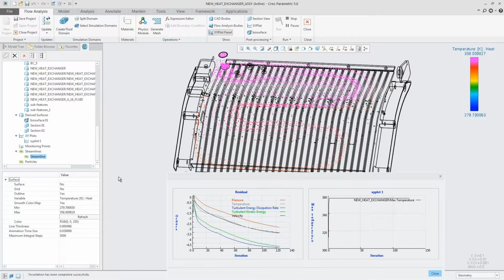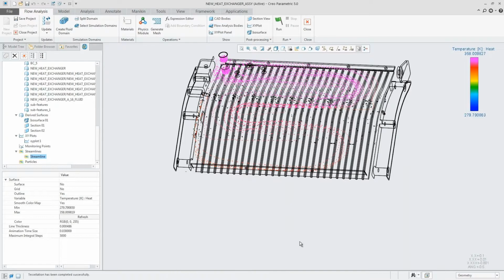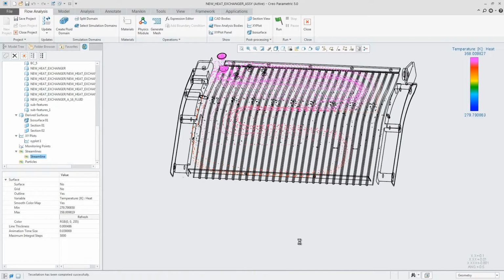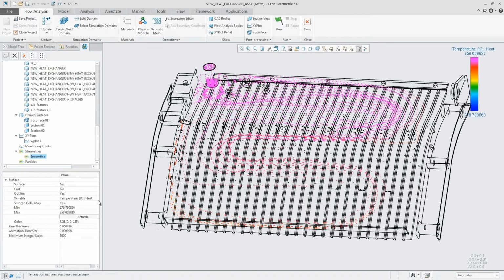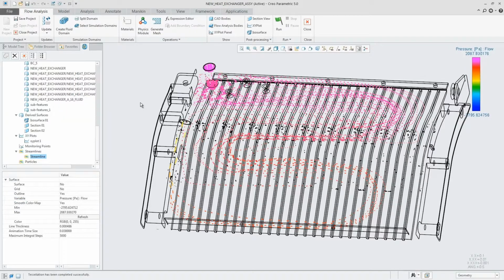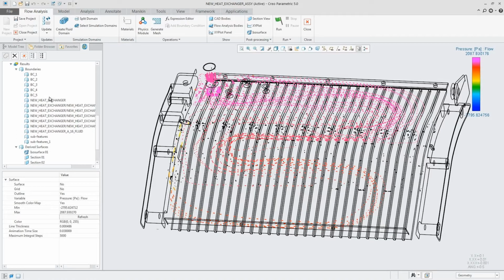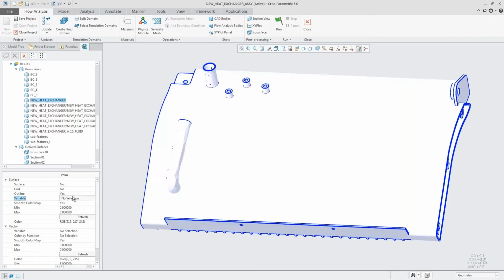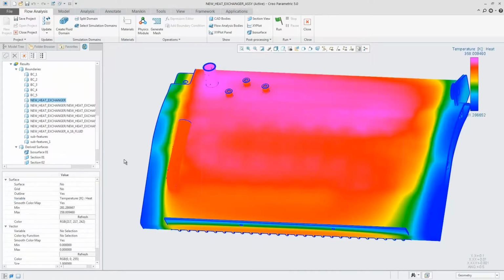Okay, and so then once that simulation is complete, we can go through, observe the flow a little bit closer, click through, change the animation properties, and see what we're concerned with. Again, we can see if we have pressure values changing and see what that looks like. Obviously, it looks a little bit different than our first example there. And now our temperature values are more spread out, and now our heat exchanger is working a lot better than even we thought it was in the first place.